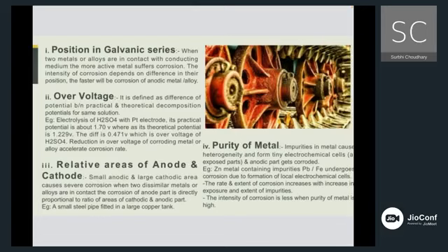As the grain size gets smaller, the surface area is more compared to the larger piece of the substance. For a metal with smaller grain size, the surface area is larger and the solubility is also higher, so greater will be its corrosion. The area under stress, even in a pure metal, tends to be anodic, and corrosion takes place at these areas. I have talked about it.